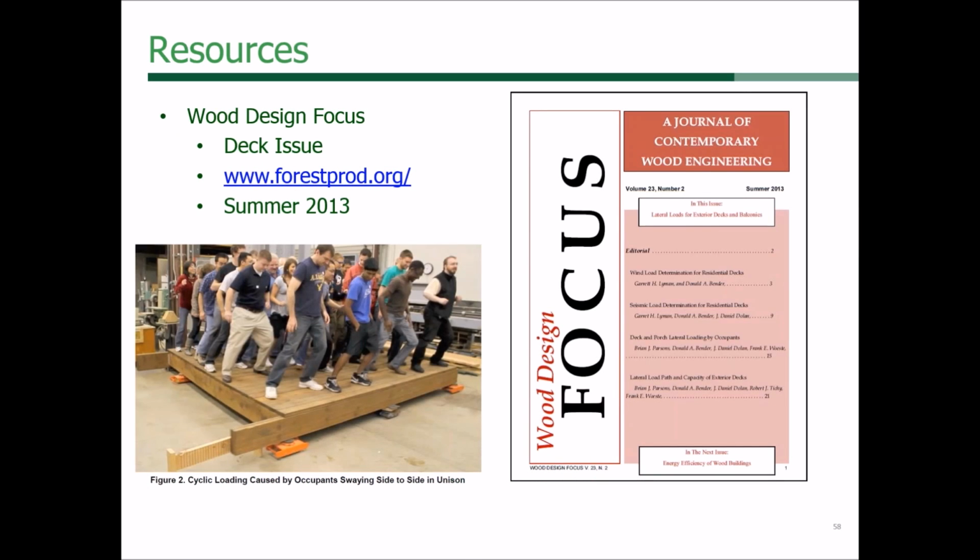Another great resource is the Wood Design Focus, and they had a really good issue talking about lateral loads on decks. And it was interesting because they did the wind calculations for a deck, and it wasn't that much because decks don't really have much sail area, for lack of a better word. And then seismic decks are pretty dang light, so there wasn't really any seismic load. But then they did that, which shows that picture right there, which is people load. And how much can people create going side to side?